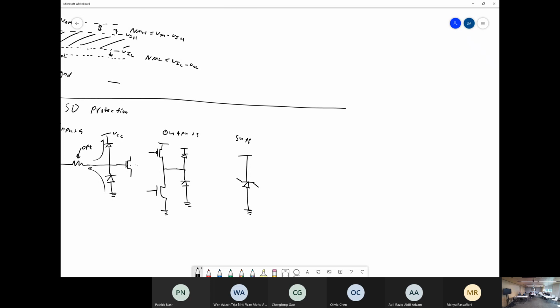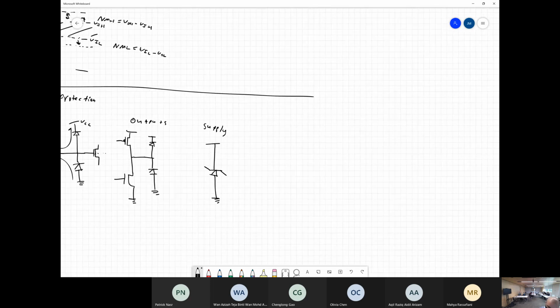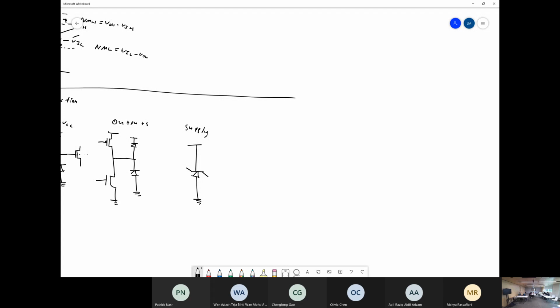So you'll always see something like this in conjunction with your other remaining ESD protection methods. Now, you can use different methods for open drain. You need to be a bit careful with open drain, or open collector. Say your output stage looks like this. This is your output terminal, which goes somewhere into your gate. So you can do the same thing: use option 1, as we've seen before, and just throw diodes sort of like this. So this is an open drain output.